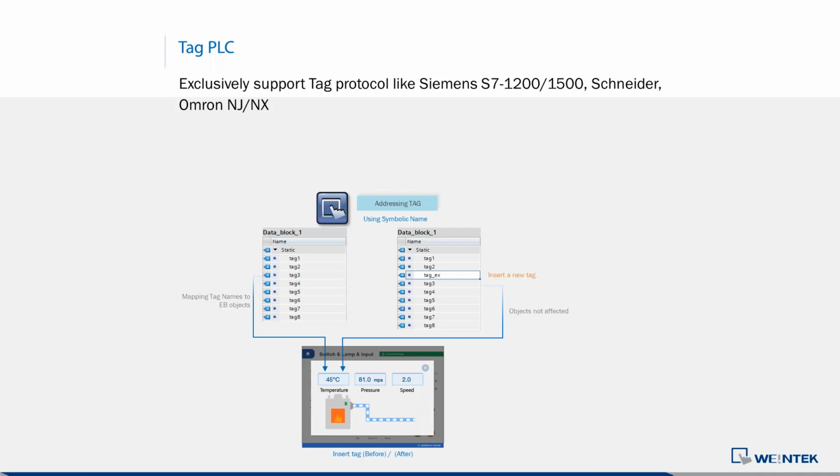They are not using the symbolic way, all right? The difference is that the symbolic way, when it is communicated with the PLC, is encrypted, so people cannot know what the PLC's register values are. But if you're using an absolute way to communicate, you can use some special tools to get the PLC's information, like what is the value of this address, what is the value of that address. But the symbolic way is encrypted, so you cannot get what is inside the PLC.